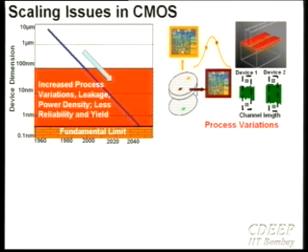And if you do a worst case design, the unfortunate thing is that your power consumption is going to go up, right? Either you have to scale up your supply voltage, and that means power consumption is going to go up. And unfortunately, area is also going to have a severe penalty. So it doesn't probably make sense to do the worst case design.